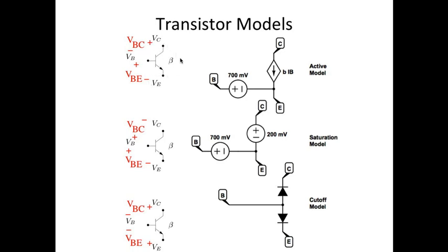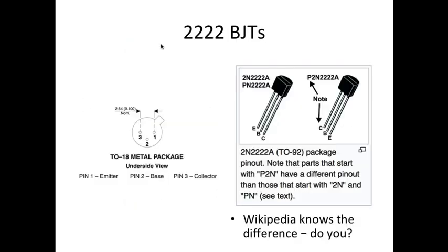It's emitter, and then base is off on the right, and then collector is on the top if you want to orient it that way. So that is a little bit backwards. Resist the temptation to bend leg 2 across so that it looks right, in quotes, according to your diagram, because there's great potential to short out leg 1 and 2 or leg 1 and 3 when you do that. The case is also connected to the collector, so shorting against the case would be bad as well.